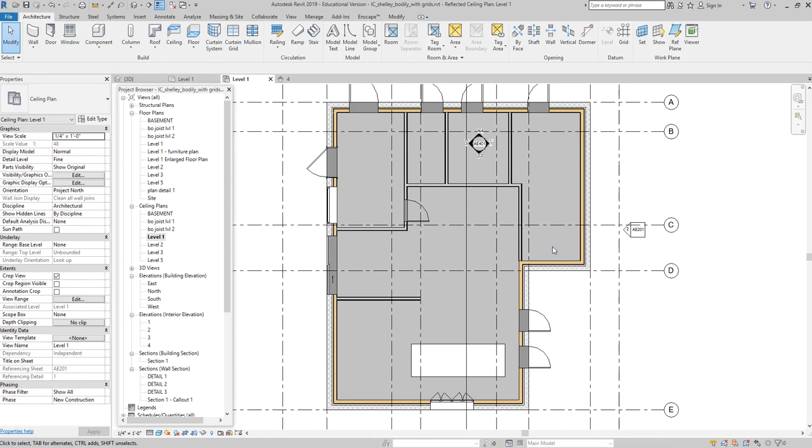The discussion we had was that a good practice is to create the structural floor, the main floor that runs the entirety of the building footprint, and then per room create individual finishes and place those pieces of floor on top of the structural floor. So you have that main structural floor integrity, and then the pieces of tile and wood floor go on top of that.